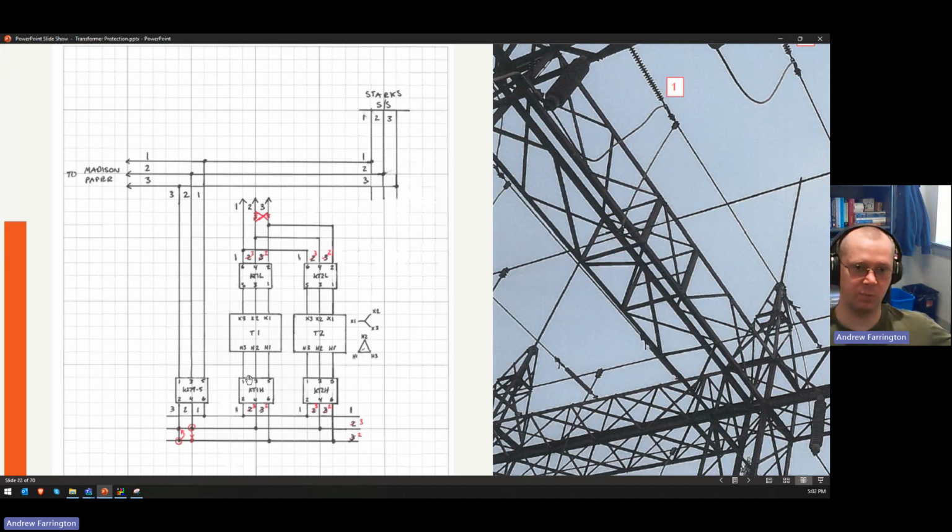So what me and Bill did, we went to the closest utility substation because we could see the phases. They had their phases marked, and we could see them from the road. So we took a picture, and then we walked the transmission line to the municipality. It was miles long, but we wanted to make sure that there were no weird taps or anything that changed the phases between there and that substation.